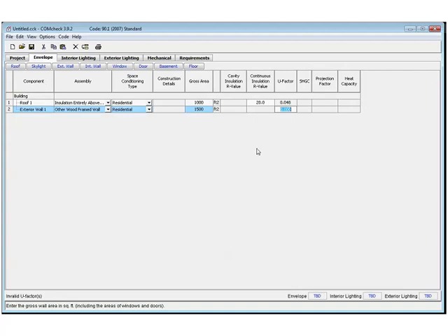And I highly advise that you provide that documentation with your paperwork to the plan reviewer or jurisdiction, because they're going to want to verify that that U factor has been calculated correctly. This one has the interior wall option, and this is code driven on 90.1, where what that means is I might have an interior wall that separates an office from an unconditioned warehouse, so I could define it using that button. But if I don't, I'm not going to choose it.